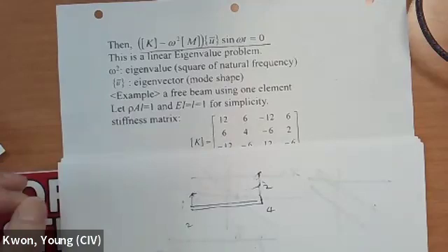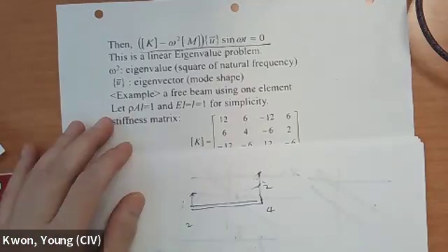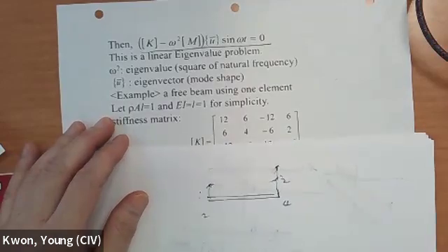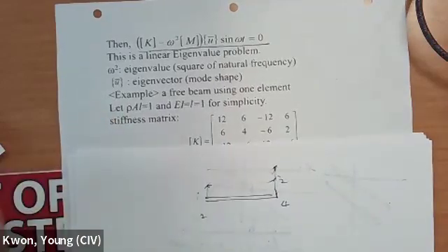So natural frequency is very important to avoid any potential failure. We don't want to operate the system close to the natural frequency. If you see an operation manual, it says you increase the motion velocity up to some point, and beyond that point you have to move quickly, because that's going to be the band of the natural frequency, that range. By moving quickly, you don't have enough time to accumulate energy, so you avoid any potential failure.